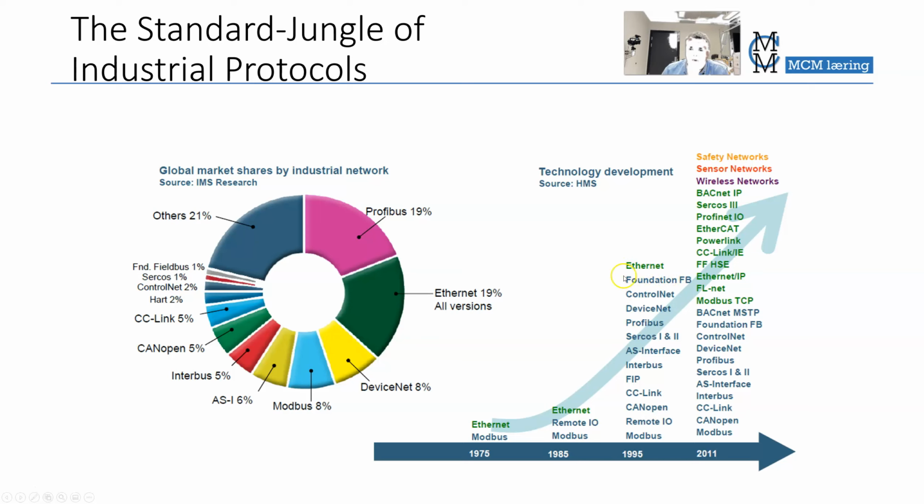Because Ethernet is so well known, even though it's not so-called real time, it's not predictable how long a message takes for a full cycle back and forth to the sensor, but it's so fast that usually the real-time problem doesn't matter. Here are a few different industrial communication protocols that will be covered in a later film. Not covered, but easily briefly presented.